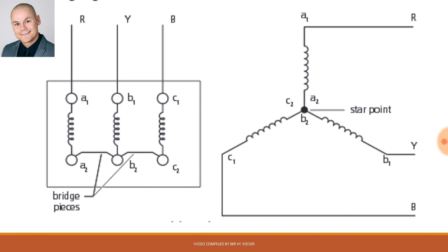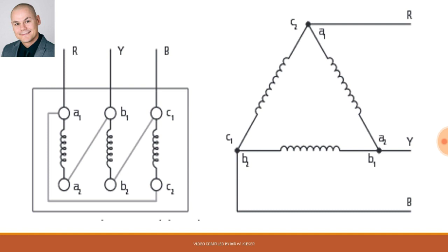Here we have a star connection, the terminal box with 6 studs for a three-phase motor. We have 3 lives, red, yellow, and blue. And these studs have stator windings connected between them. We've got 3 coils, and they're labeled A1, A2, B1, B2, C1, and C2. Now, in order for this star connection to be bridged at the neutral point, we have to connect up A2 to B2 and C2 to B2. And by bridging those studs, we're able to connect this three-phase motor in star.